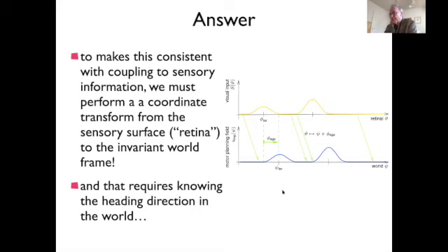To generate the motor control, the behavior, you just need to know the rate of change of heading, which is the rate of change of speeds you send to the motors. But for making this transformation, you need to know the value of the heading, and that actually only shows up when you want to use something like working memory, so when you want to represent sensor information in a way that's not directly specified by the current sensor information.